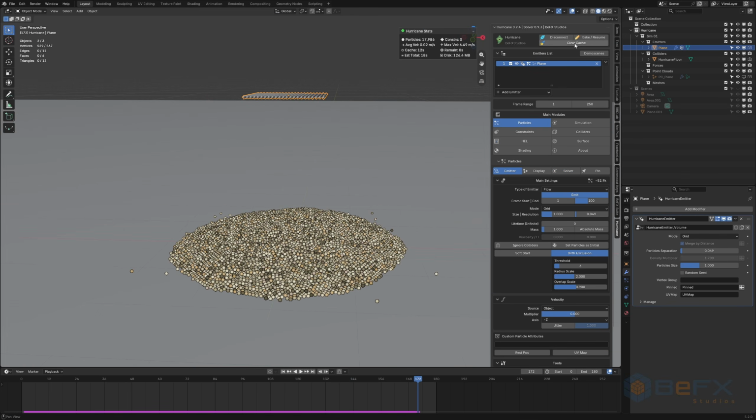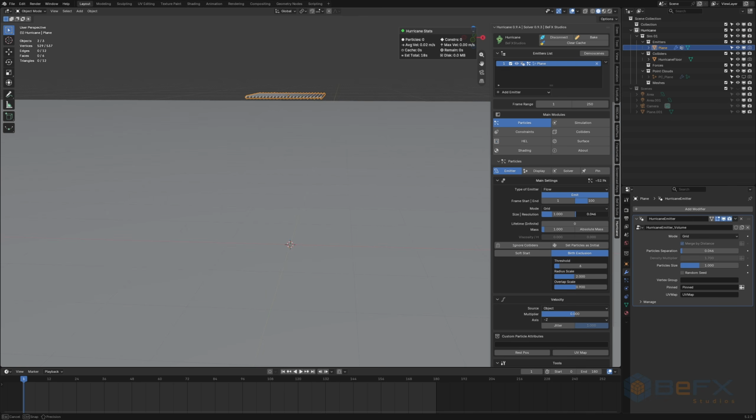Let's increase particle density even further to test a super useful feature called sleep. With sleep, we can define specific conditions for particles to go to sleep. Based on a minimum lifespan and velocity threshold, particles freeze, removing all movement while keeping their collision active. This allows the sand to pile up stably, forming a mountain without collapsing.